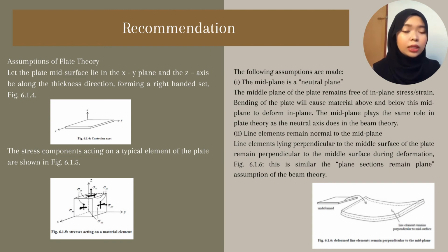The mid-plane is a neutral plane. The middle plane of the plate remains free of in-plane stress or strain. Bending of the plate will cause the material above and below this mid-plane to deform in plane. The mid-plane plays the same role in the plate theory as the neutral axis does in the beam theory.